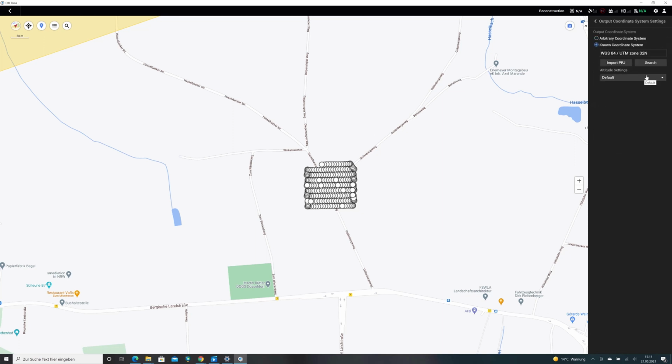The arbitrary coordinate system will take the projected WGS84 datum for the area in which the photos were captured, but a different output coordinate system can be chosen if desired. The default elevation will take the ellipsoidal height, however, geoidal heights can also be chosen.